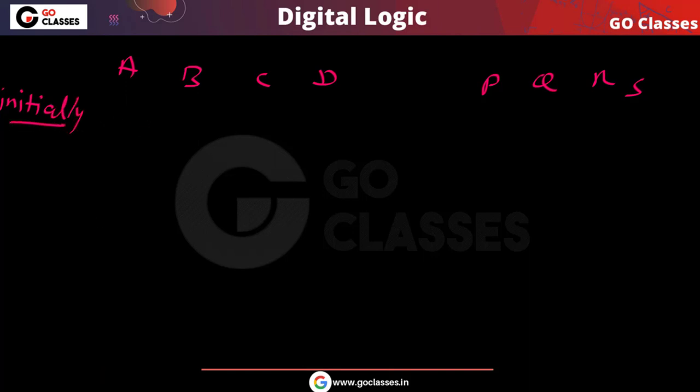Initially, the content of this register is 1011, and the content here is 0101. Now after one clock pulse, what will happen? Let me call it t1. After one clock pulse, very simple, every data you are shifting, so this will be shifted.